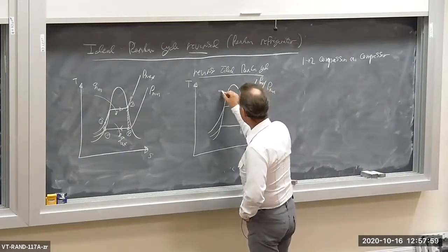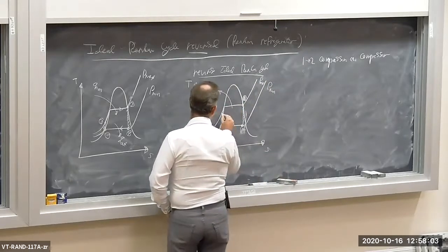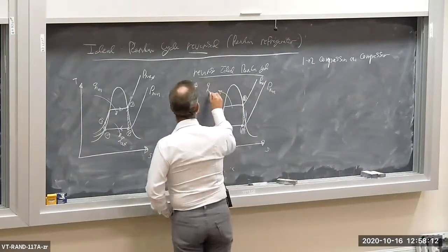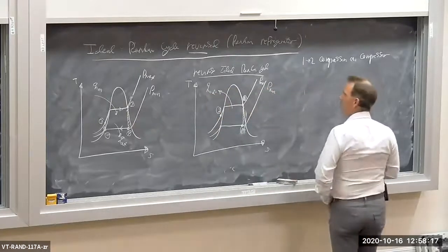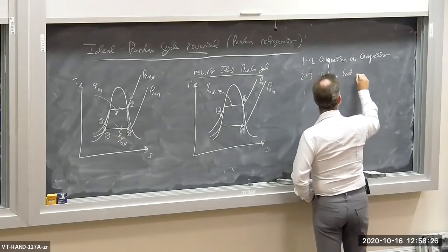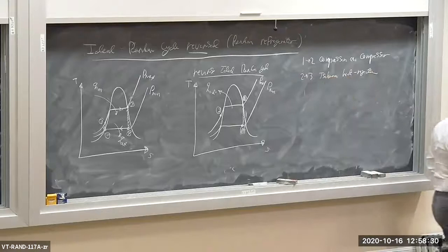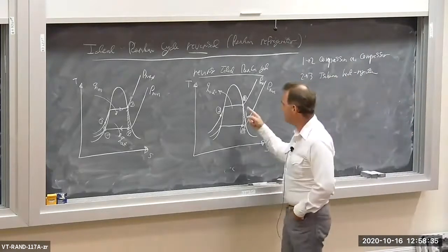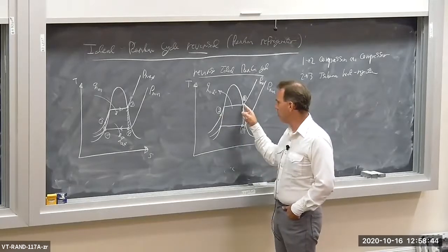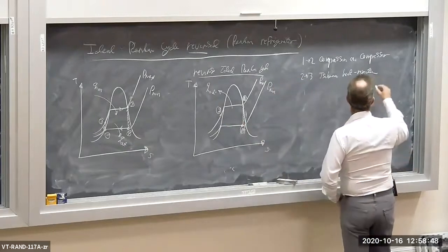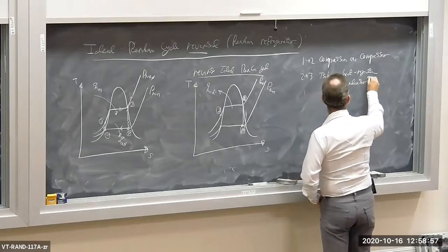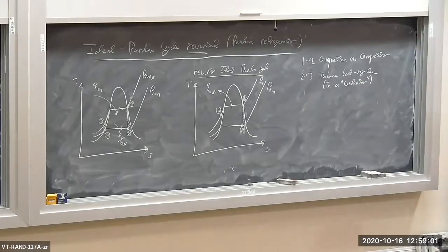Then we have heat rejection, constant pressure at high pressure, down to state 3. So we have heat rejection output, Q out. I'm just reversing the direction of the Q in, and it becomes a Q out. So process 2 to 3 is isobaric heat rejection. By the way, we're starting off with a saturated vapor and we're going to a supercooled liquid. So we're condensing the working fluid. We're going from a vapor to a liquid, so we're condensing the fluid. So this is in a, quote, condenser, okay? In the condenser, the boiler became a condenser. That's nice.